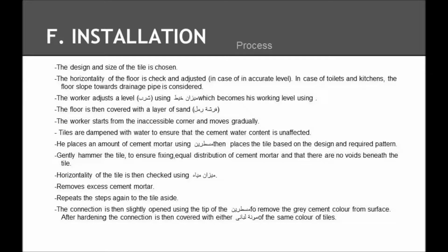Now, when placing, the tiles are dampened with water to ensure that the cement water content is unaffected. The worker then places a certain amount of cement mortar and then places the tile based on the design and required pattern. And then, ever so delicately, the worker will gently hammer the tile to ensure equal distribution of cement mortar and to ensure that no voids are found beneath the tile.